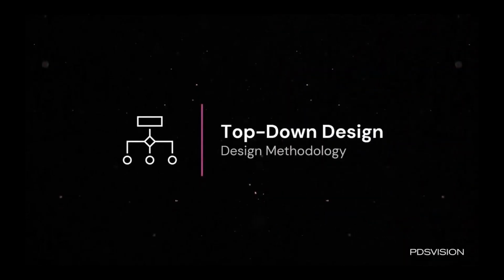But let's start by talking about a design methodology, something that we call top-down design. If you're used to building your products in a certain way, maybe building your parts first and then assembling them together, that's something we call a bottom-up approach. You're working at the small level and then building up larger beyond that. This approach is really good. It's quick, it's fast, and works really well for simple designs. But when you're starting to deal with larger designs, larger assemblies, more complex assemblies, or you have more people working on your products, that approach begins to fall apart a little bit.